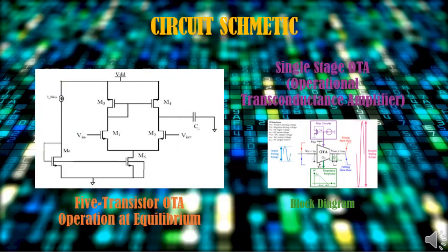So for our circuit schematic, based on the reference paper, they use an OTA operation. So what is OTA? The design that we use is the single stage operational transconductance amplifier. Essentially, OTA is a voltage to current converter where the voltage is converted into an output current.